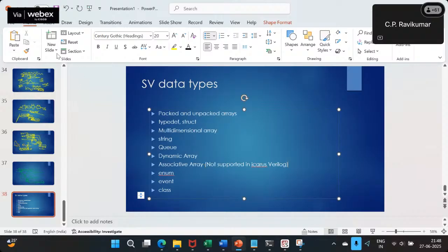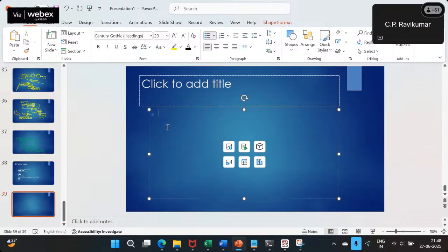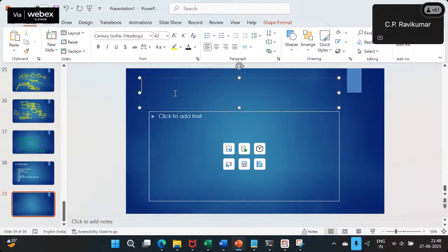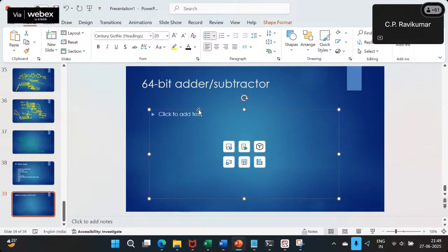So you can try, just like the BCD adder, try if you can create an n-bit adder subtractor. When n is large, suppose you wanted to do a 64-bit adder, then you can't design it as a ripple carry adder. So you'll have to try the method I discussed today, or some similar method.